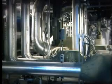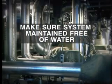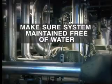In operating any of the steam systems, one of the most important operating requirements is to make sure that the system is maintained free of water. In this segment, we have looked at typical steam systems, but of course all plants are different. Make sure that you become familiar with all of the features of your various steam systems. That is main steam, reheat steam, extraction steam, and auxiliary steam.